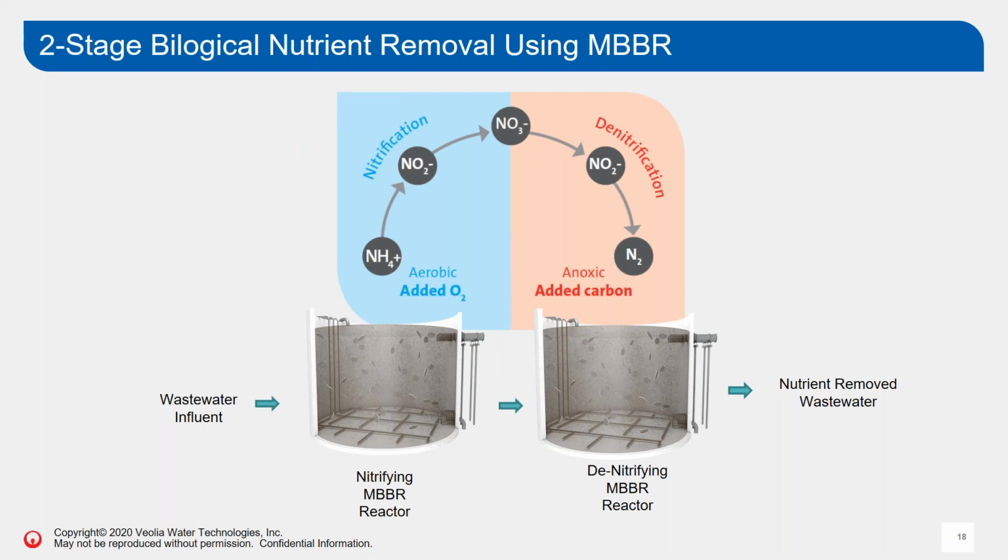When we talk about nitrogen removal biologically, we're basically talking about two subsets of biological processes. So most often, with some rare exceptions, which are important, we see nitrogen in the wastewater in its most reduced form, and that's ammonia. Ammonia, prior to removal, needs to be converted to nitrate and nitrite. And that process is called nitrification.